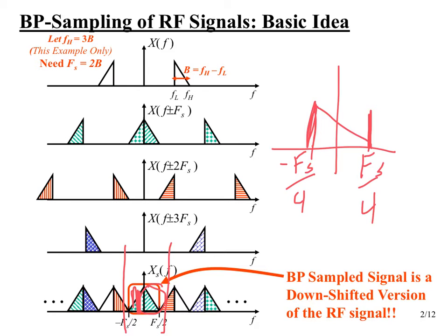And we're actually a little oversampled at that point. So we could, as we talked about in one of the earlier sets of notes, reduce the sampling rate by a factor of 2 at this point. So this would give us the equivalent low-pass signal at this point. So bandpass sampling is a preliminary step that could be used in principle to replace the analog electronics that does the frequency downshifting involved in creating the equivalent low-pass signal.